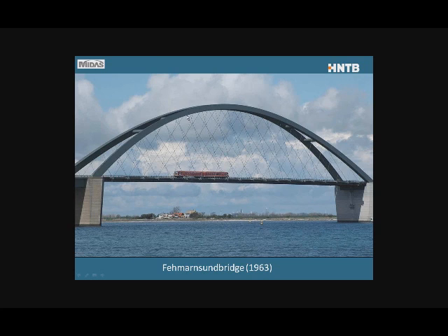A network-tied arch is characterized by the set of inclined cables. You can see here two sets of cables in each cable plane. So instead of vertical, like the conventional tied arches, they're inclined. And the crucial part of the definition, Per Tveit, is that some of these cables have to cross at least two other cables. So if I take, for example, this cable here, that's actually been crossed by 1, 2, 3 other cables. So that's what makes a network-tied arch a network-tied arch.